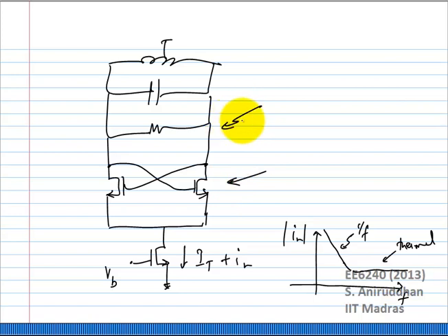How will that appear at the output? It will get upconverted, multiplied by some omega naught. So instead of having flicker noise around DC and then thermal noise, what you would actually expect at the output is around F naught. You would maybe expect 1 over F flicker and thermal. Maybe you might expect something like this. Okay, around F naught you may expect to have 1 over F and thermal, so you may get that shape.